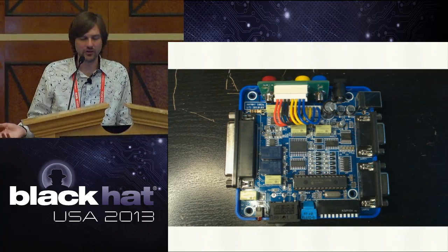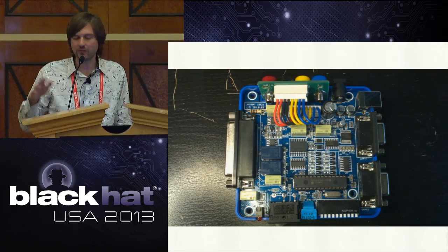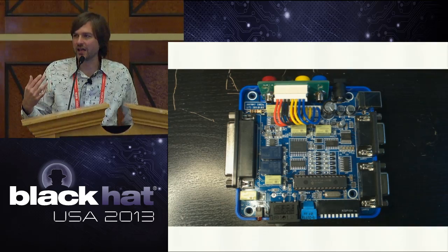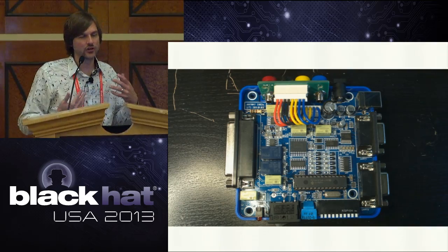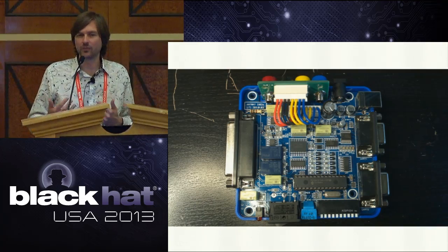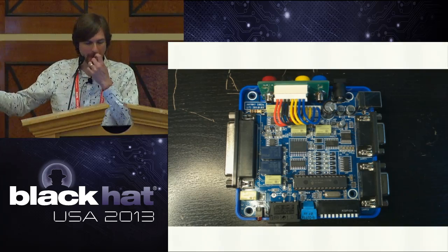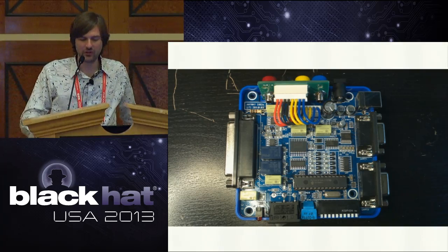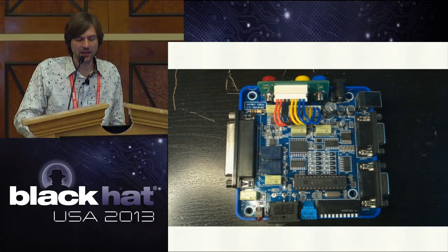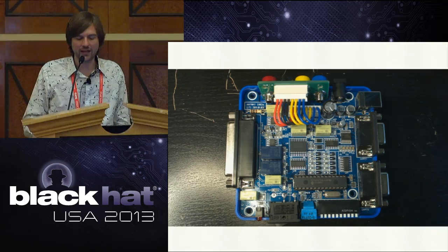But the inside of this device is not too interesting. There's a PIC microcontroller that controls everything. There's a bunch of power switching stuff, because a big part of what this device has to do, apparently, is charge or power a wide variety of different target devices that are plugged into it. So a lot of the surface area, a lot of the volume of this device, is just taken up with power electronics. And then there's this grid just above that long DIP package microcontroller.